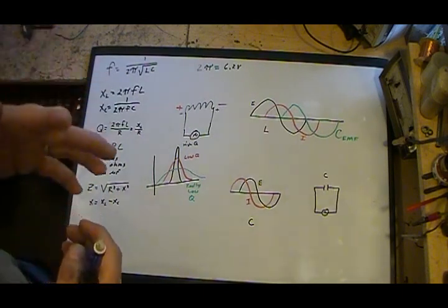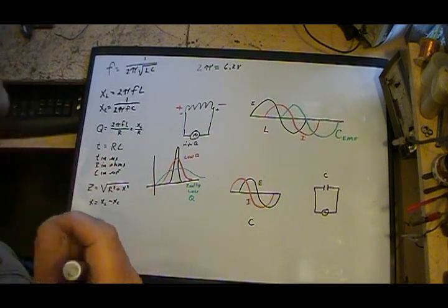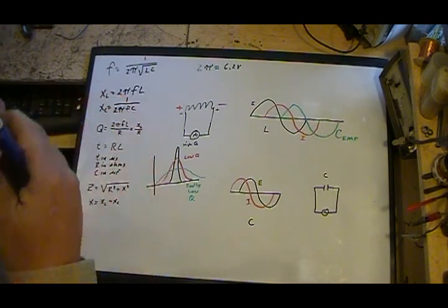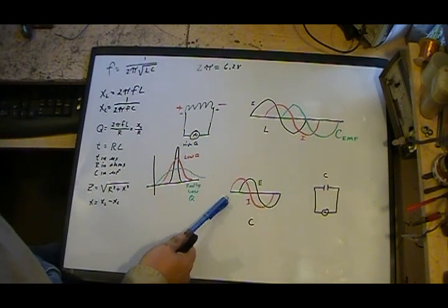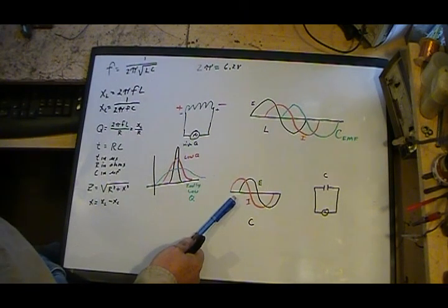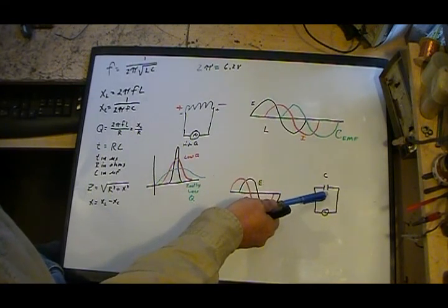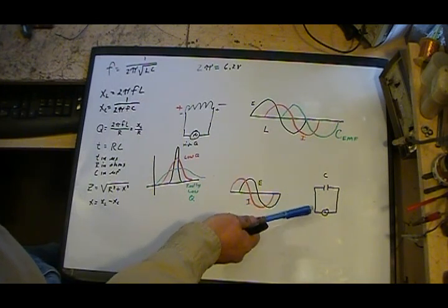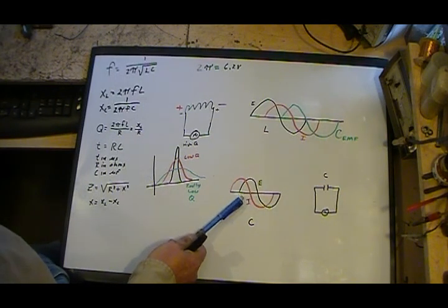But if you take like a 20 or 30 or 40 microfarad electrolytic and start checking it, it's going to take a while for it to build up the charge. Well, that time it takes is what causes this lead of current. The current will still flow as it charges the capacitor and builds up charge on the capacitor before you actually start getting a voltage to show up on that capacitor and in the circuit.